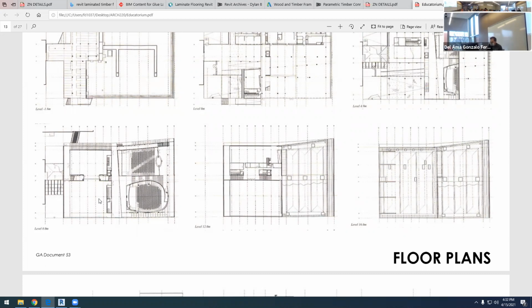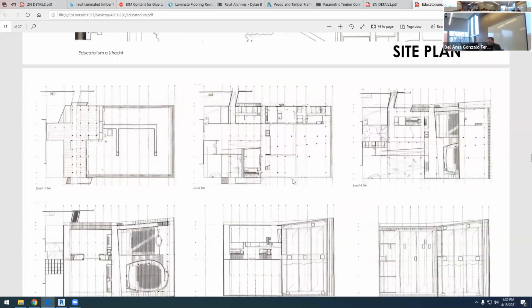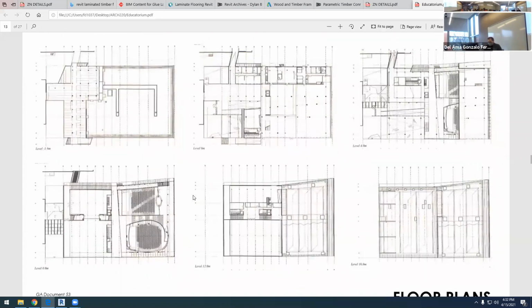We have a load somewhere, and by means of vertical and horizontal structural elements, we need to carry this load up to the ground. So the most efficient way is having a vertical element. If we have a load and I have a vertical element that goes from the load to the ground floor, that will always work. So even if we have a weird building, gravity exists, and having grid lines with columns there is always good advice.